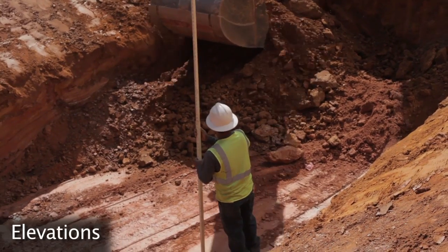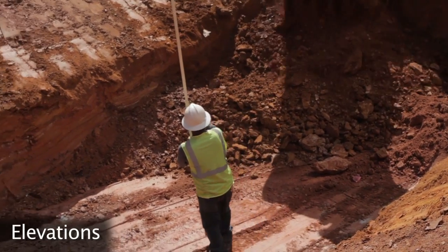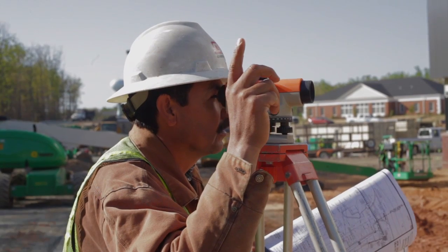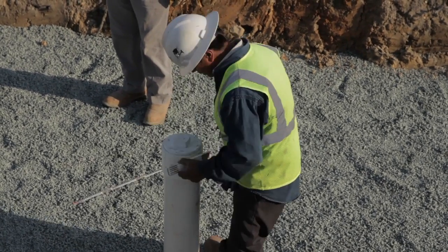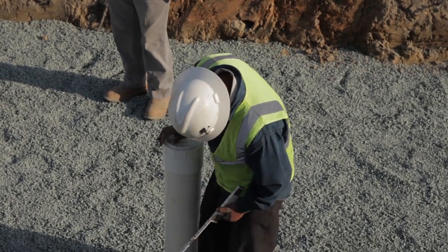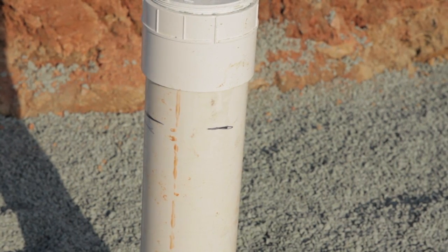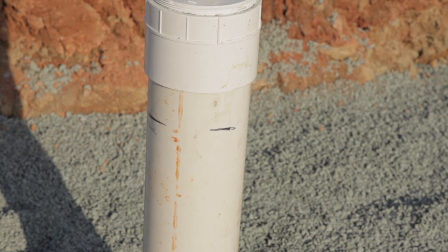If any of these materials are incorrect or improperly placed, the filtration process can be slowed, or the removal of pollutant by the soil and gravel media can be negated. Along the way, it is important to check the elevations of surface and subsurface layers, underdrains, berms, inlets, and outlets to ensure the function of the practice. Even minor deviations can result in significant problems with the overall function of the practice. Here is Ted Scott, who discusses a failing system due to improper elevations.